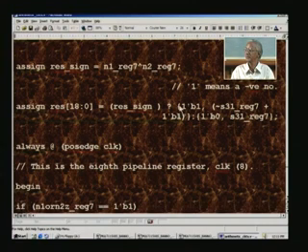So this is clear here, there is one statement here and another here. This statement is executed if this is 1, otherwise this is assigned to the final result. Either this is assigned or this is assigned, depending upon the sign bit here. So here we have appended 1 because this is going to be a negative number, and we have appended 0 for a positive number. Either this 1 or this 0 will reflect as result 18, that is the MSB. So this tells you how we take care of the sign bits as well.